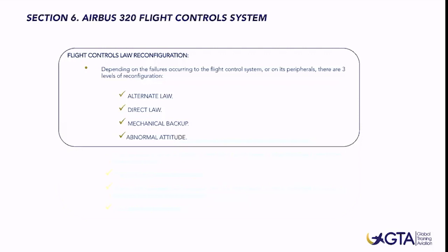The difference is that the pilot can override this demand. I mean, in this alternate law, if we get into this low speed stability, if the pilot pulls the stick back again fully deployed, we will enter, in this case, a stall condition. So be careful with that. We still have audio stall warnings, and the PFD scale is modified as we will see in the next slide.